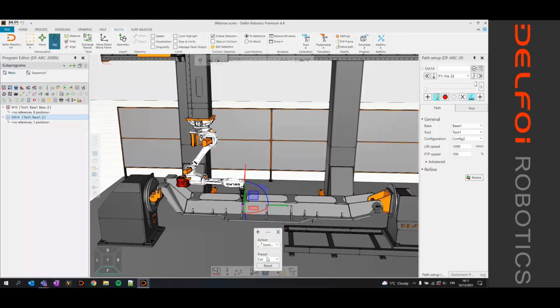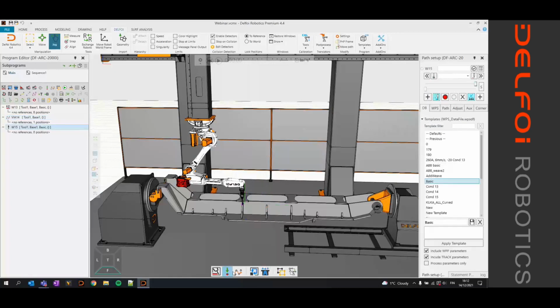So we can switch to the cut application, where you can see that it adds the drill path over here. We have spot welding tools that will then open up a spot gun tool over here. Then we also have surface tools, painting tools, and T-scan tools. And all of these are modifiable, so you can add your own actions, you can add more buttons into this, and then you can also switch those tools that you want to have over there, or you can even add spacers between your tools if you want to space them in a specific manner.